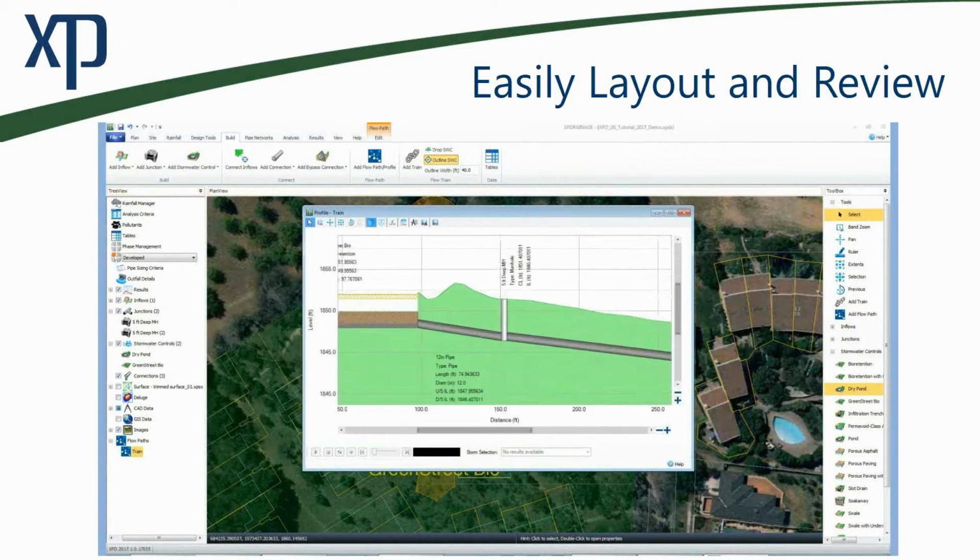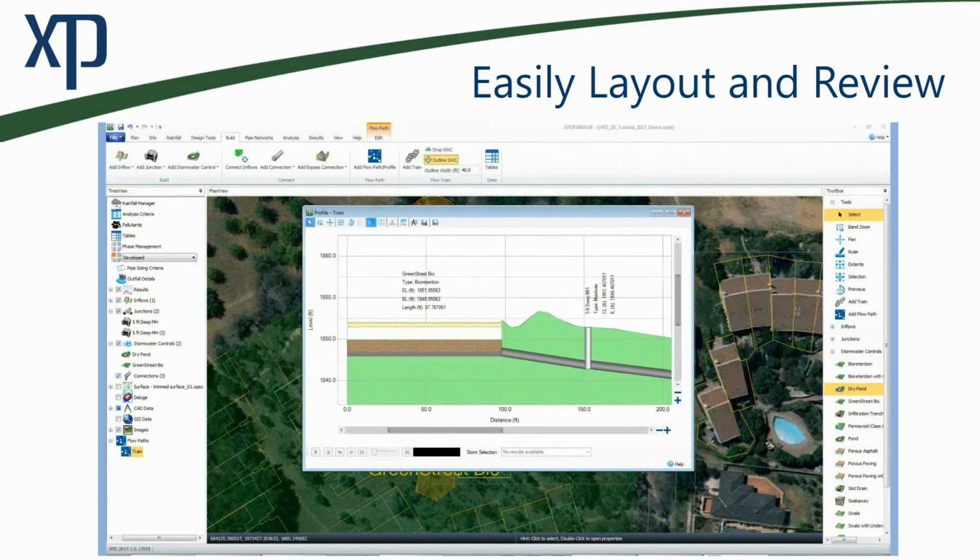You can see here in this video, it just takes a few seconds to lay out the items in a system. And because I have a surface, because I drew this to scale, all the input is automatically set for me. This might not be the final elevations, might not be the final finished plan, but it is really quickly a 90% level of detail, making sure that everything can gravity feed or daylight out into a pond, and so on and so forth.